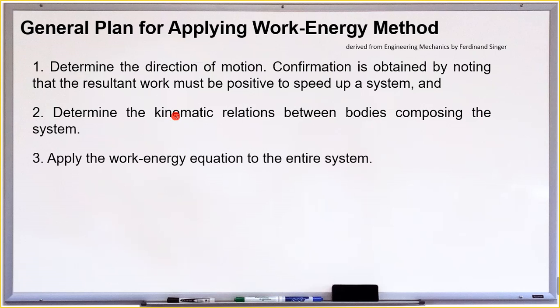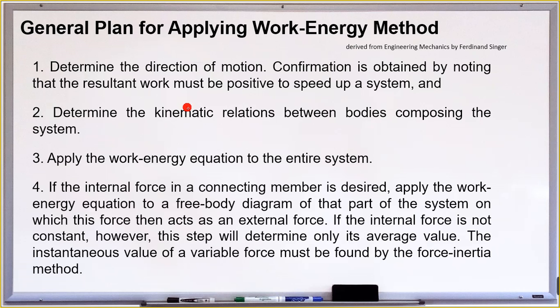The third one: after determining the direction and the kinematic relations, proceed and apply the general equation for work and energy. And the fourth one, if the internal force in a connecting member is desired, we neglect it for now, because of course the tensions cancel out. So apply the work-energy equation to a free body diagram of that part of the system on which this force then acts as an external force.